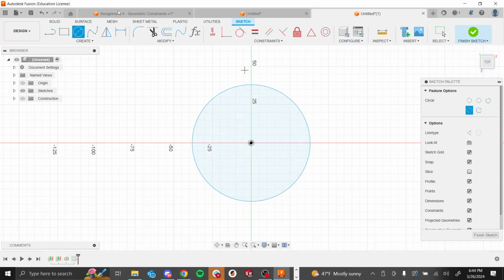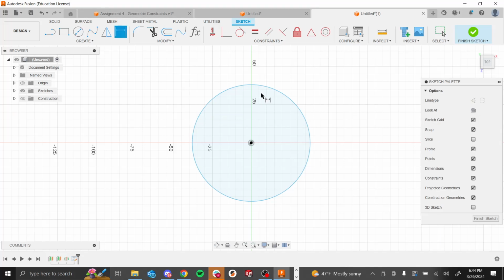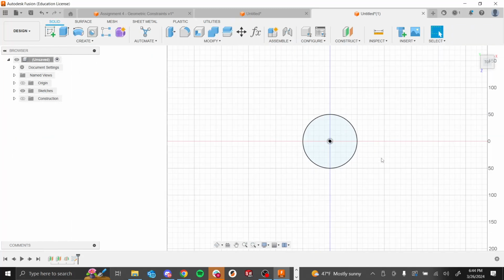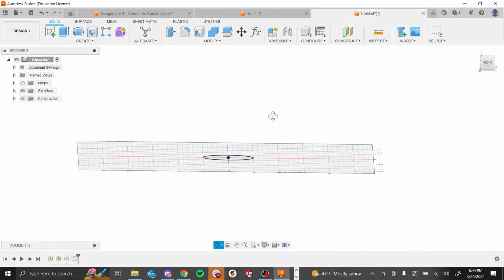So I'm going to start by making a circle. I'm going to make sure it's at the origin, just for simplicity's sake, because we're going to create 4 different circles, but we want them all to be kind of on the same line. So our hairdryer looks straight and it's not bendy, if that makes sense. I'm going to assign it a diameter, maybe I'll just start with 100. So we have our circle.